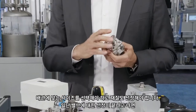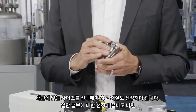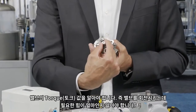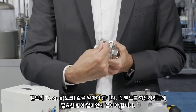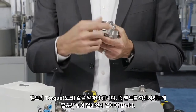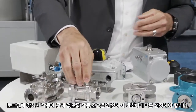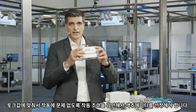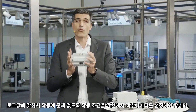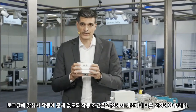Once you know what is exactly the valve that you need to install in your process, you know what is the breakaway torque, which means the force that you have to apply in the shaft of the valve to be able to operate this valve. With this information, once you know this, you need to go to select the quarter turn actuator that will fulfill the function that you have defined.